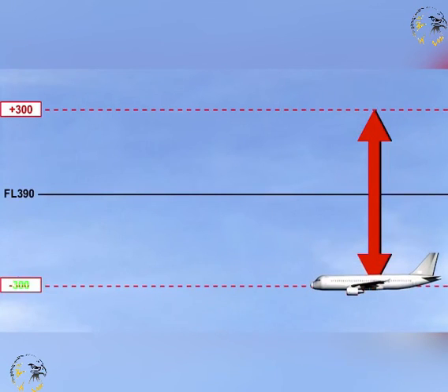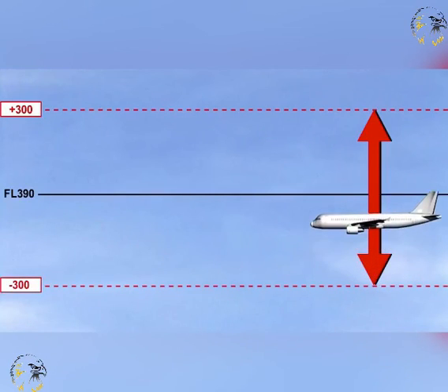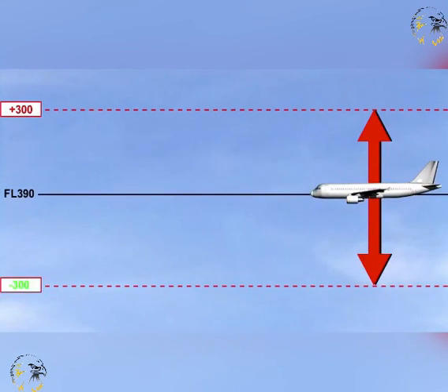An aircraft climbing or descending is considered to have crossed a level when the Mode C derived information indicates that it has passed the level by more than 300 feet. Ground controllers will require confidence in the SSR accuracy of an aircraft, and an aircraft will be considered to have reached a flight level to which it has been cleared when 3 consecutive renewals of the Mode C derived level information have indicated that the aircraft is within 300 feet of the assigned level. In this manner, all aircraft using a piece of airspace will be accurately tracked. This completes the lesson on general radar services.